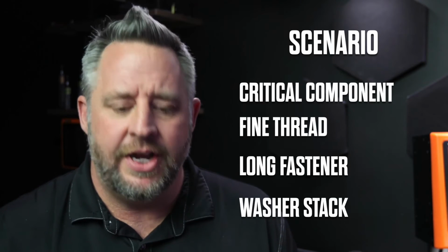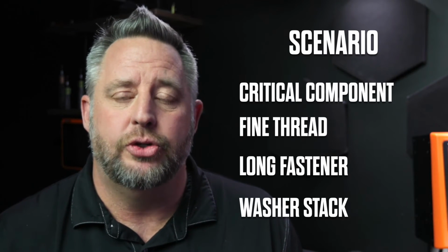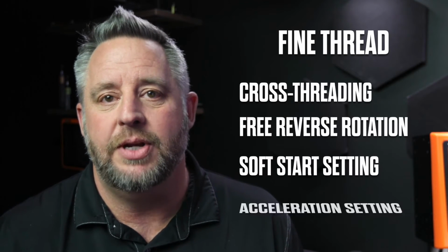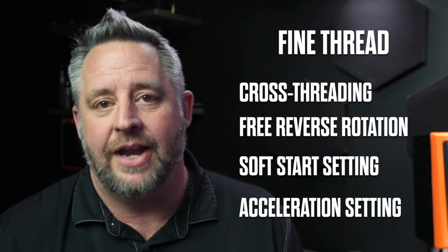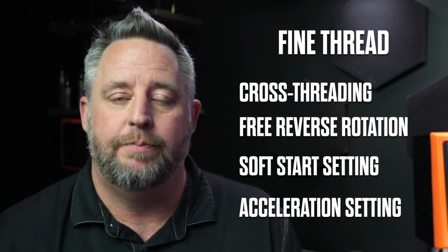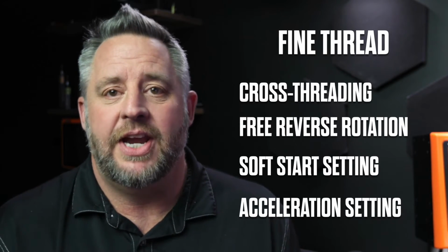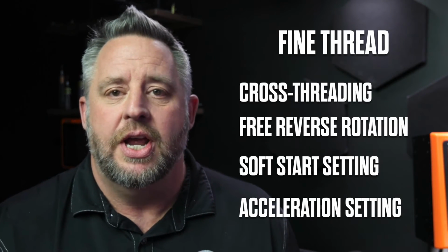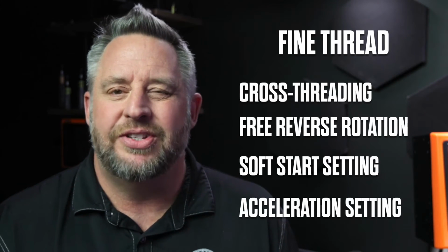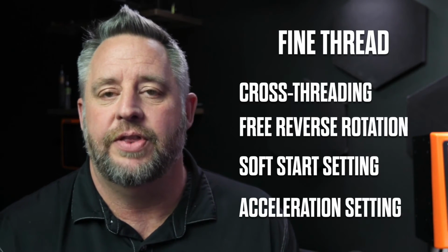And so one of the things that can happen very often with an electric tool and a real fine thread fastener is the ability to cross thread that particular fastener, and that can happen very, very easily if the operator isn't paying attention. So what are some of the things that we can do to help alleviate and remove the cross-threading issue? Within our system, we have a free reverse rotation. What this does is it allows the tool to spin in the opposite direction of the tightening.